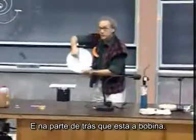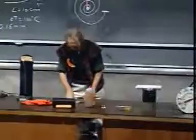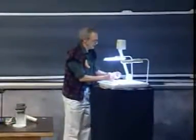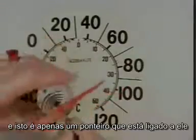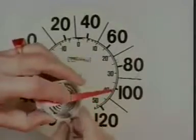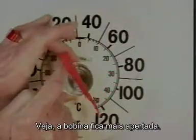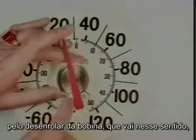And in the back is this coil. And so I broke one open for you in order to make you see that coil. So I have that here. This is the part that is in the back. And this is that bimetal, the bimetal coil. This is the bottom part. This is the top. And this is just the hand that is attached to it. And then it goes into this case. Let's make sure that the pivot goes in there. Yeah. If I increase the temperature, try to see that you see the coil tightens up. See the coil gets tighter. And when I make the temperature go down artificially now by uncurling the coil, you're going to this direction.